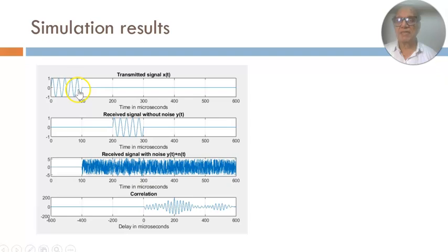Note that the correlation of the transmitted sine wave with the noise is going to be very small, because the random noise changes in a haphazard fashion. There is no similarity between noise and the sine wave. So when you calculate the correlation between the sine wave and the noise, that part is zero.